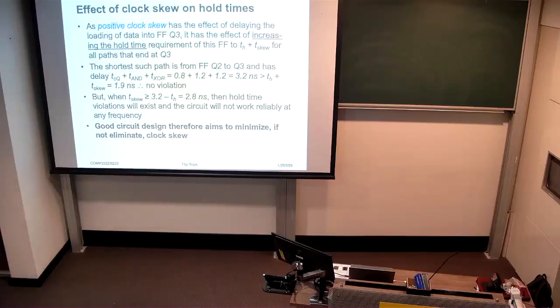You do not want to introduce clock skew. And where that is practically seen by you guys in the lab is you should never, for example, add additional delay or additional gates into the clock signal for any flip-flop. Always have just a pure clock signal going into a flip-flop. Rather than controlling the clock to control whether a flip-flop operates or not, you should do that synchronously on the data inputs, and control the value of the data input, not whether the clock is working or not, because that will introduce skew. Okay, so that's covered those slides that we missed.